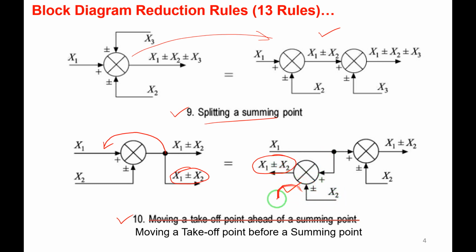I hope you got it, right? So whether I move the takeoff point before a block, before a summing point or after a summing point, one more summing point gets added. The hardware increases. Please keep in mind, takeoff point and summing point. So this is rule number 10.